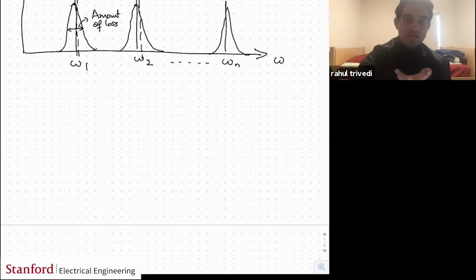In practice, so essentially then, what is it, a cavity or not? It's more of a question of, if you find a high Q, a very narrow line with resonance, then you can think of it as a cavity. But if you look at these artificial problems where you put a PEC boundary condition, then of course you might have resonances that would exist in a PEC problem, but they're artificial. The moment you remove the PEC boundary condition and come back to the real world, those resonances are going to disappear because they're just going to be incredibly fast. Okay, does that answer your question?